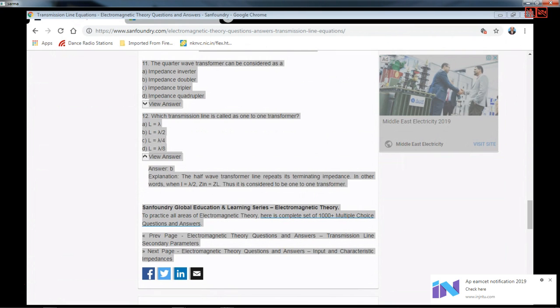Okay, so 2 beta z prime is the distance you are moving from the load. So theta gamma, that is the phase of the reflection coefficient, is going to vary by theta gamma minus 2 beta z prime, and it must be equal to -pi. Why should it be equal to -pi at the location of the voltage minimum? Because a voltage minimum occurs only when the reflected voltage and the incident voltage are opposite in phase.